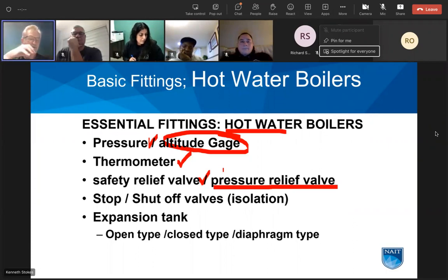Steam is compressible. When the pressure is too high, we need to get rid of the pressure immediately. Because water is not compressible, when that relief opens, the pressure is basically zilch immediately. There's no reason to exhaust what's in the boiler. Safety pops, pressure is dropped down.